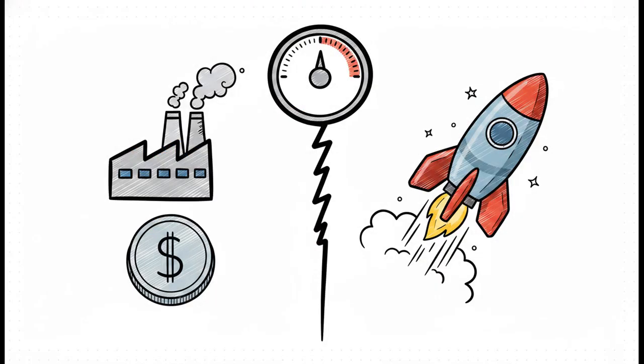And you know, the very first dial you're going to turn is purity. On one hand, we've got technical-grade alumina, which sits at around 85 to 96% purity. Now, this grade is super cost-effective. It's a fantastic, versatile baseline for general industrial use. But if you're designing for truly demanding, high-performance environments, you absolutely have to pivot to high-purity grades. We're talking greater than 99.5% pure. Hitting that level of purity means extensive refining to pull out trace elements, which, yeah, definitely increases your costs, but as we'll see in a minute, it is absolutely crucial for unlocking superior electrical and structural performance.